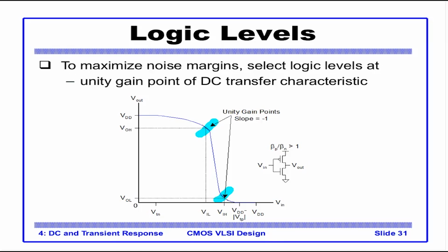So what we are defining here is that at these slope points, the output changes from VDD and immediately goes into a very sharp region. This is a very sharp transient region. So we don't want to go into this. We want to restrict ourselves to this particular region, for input voltage 0. The voltage here we define as VOH, and the corresponding input voltage. This is the output voltage corresponding to this slope, and this is the input voltage. So we call this VOH and VIL.